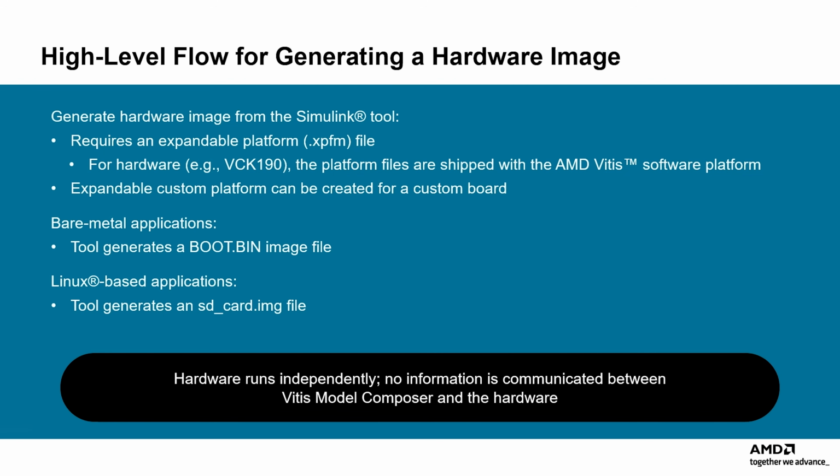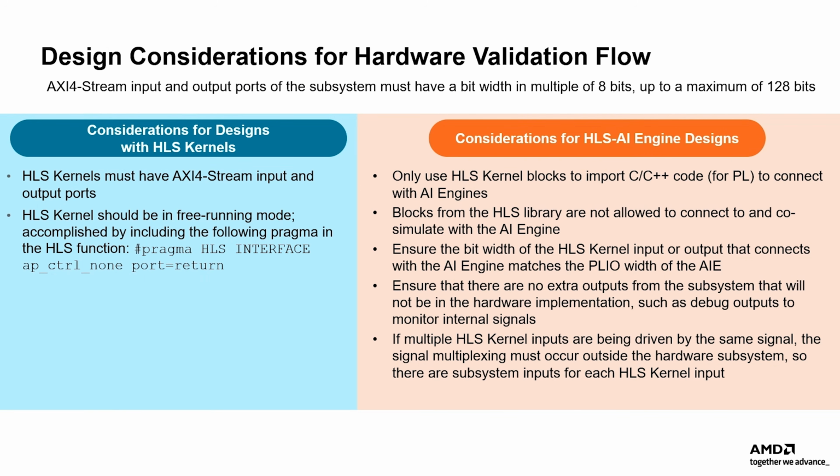Unless something is wrong, the result should match bit by bit with the results of the simulation because the simulation in Vitis Model Composer is bit accurate. The hardware runs independently, and during the hardware run, no information is communicated between Vitis Model Composer and the hardware. Review the following design considerations for the hardware validation flow for AI engines and PL designs.